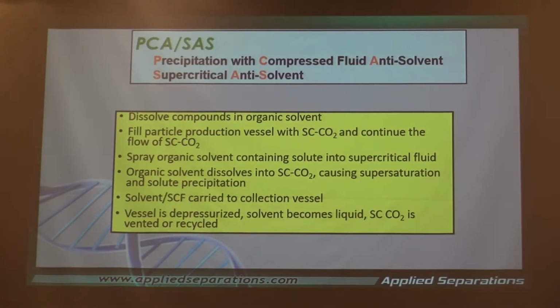Gas SAS. Again, like I said, I don't know where they come up with these names. But here's what we're going to do. We have our compound that is dissolved in the organic solvent. This time what we wind up doing is we fill it with CO2. We're going to do it a little bit backwards. The first time we filled in the solvent and the solute and then brought in the CO2. This time we're going to go ahead and put in CO2. And we're going to keep the CO2 flowing.